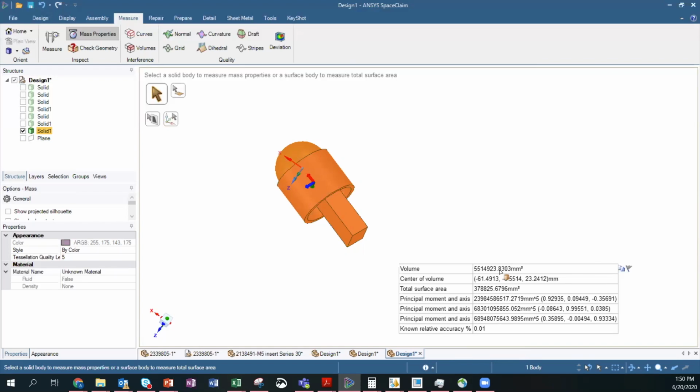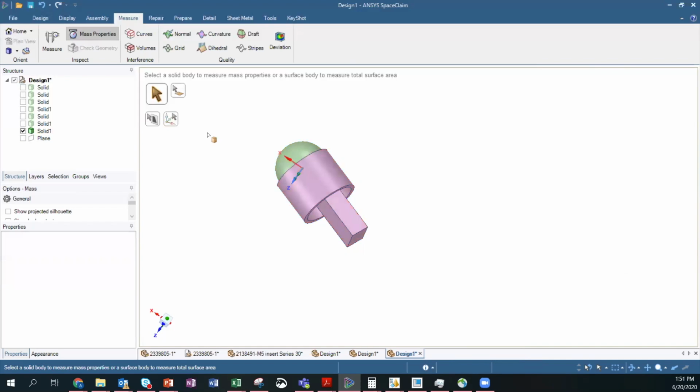So if you input the density over here, you can also get the moment of axis, since the moment of inertia: IXX, IYY, IZZ, all these things you can get. You must have studied it for a sphere or cylinder, but this is more complex. So the software helps you get it right there. And the volumes you can get too.